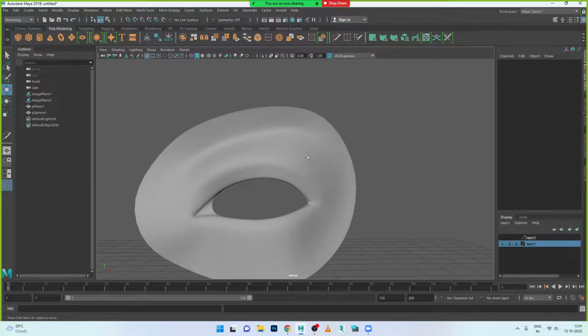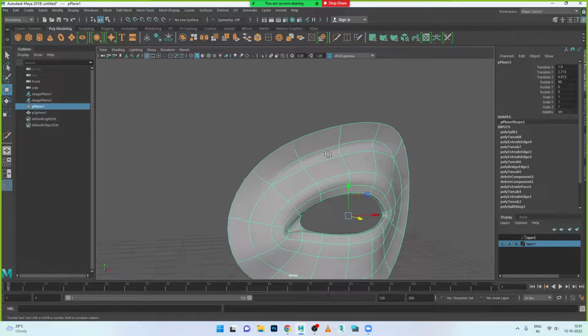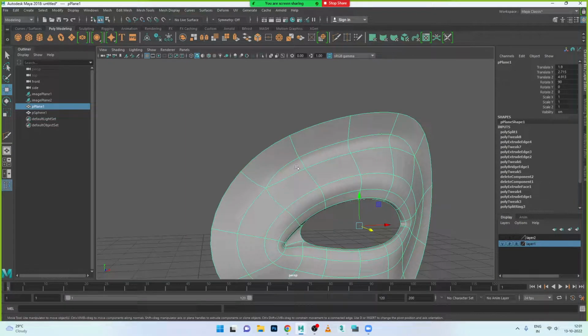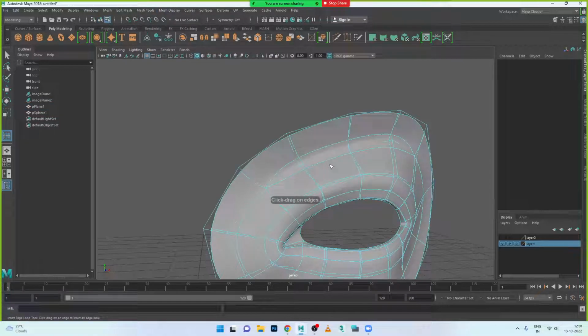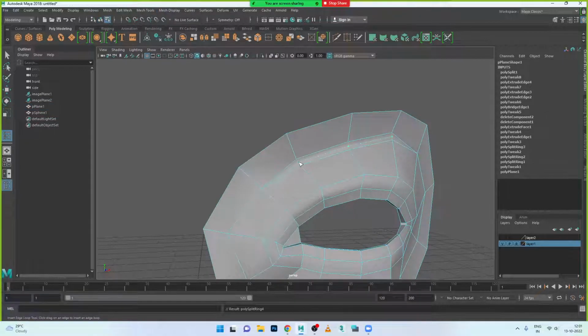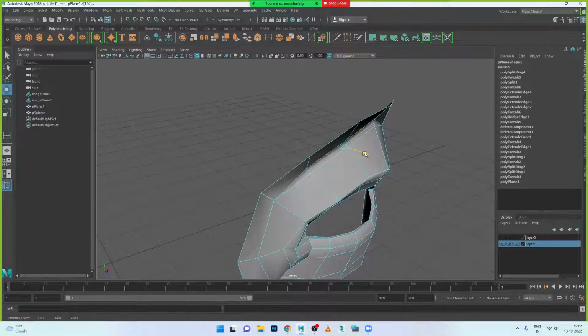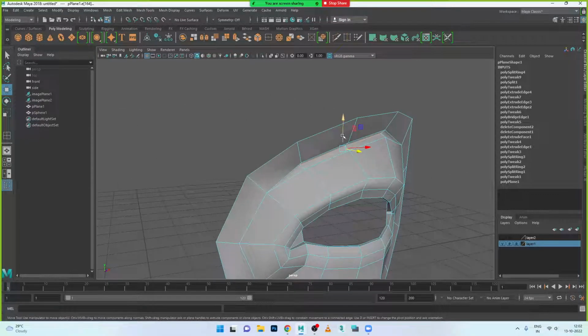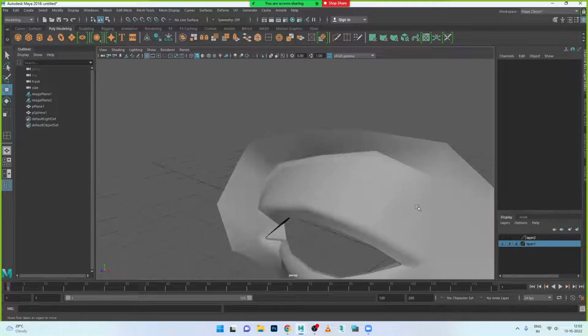Can you see the depth in this? More deep we want it on this one. Okay, more deep if you want, what we do, so in this one we'll add one more edge inside this one now. So what we'll do, we'll take this mesh tool, inside edge loop tool, and try to add, press 1 and add one line on this side now. Take this edge, select this edge and try to apply more deep in this now, and try to move up a little bit. Okay, right click on this one, object mode, and press 3 and see now.